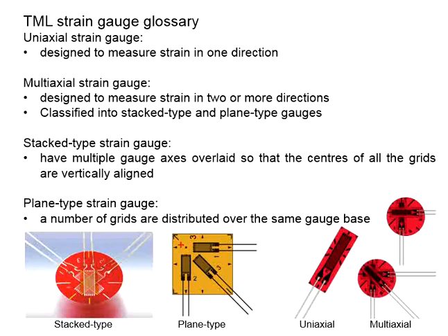You are measuring the elongations or the strain, which refers to this point in these directions, and this direction. To be more specific, although it is placed at this point here, what you are actually measuring is the elongation at this point, at this point, and at this point.